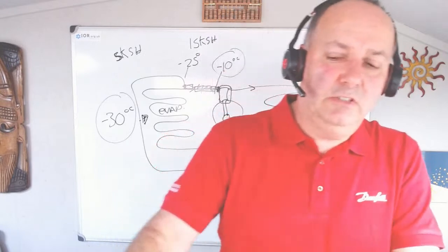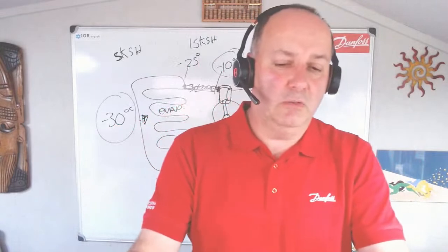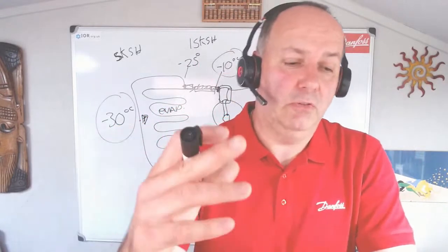Okay, Dwayne, which connection of the evaporator during hot gas defrost is optimal for commercial refrigeration systems? And that's from Gregory. It depends what we're talking about, whether we're talking about the simple reverse cycle, whether we're talking about literally putting hot gas into the evaporator on a 1-to-1, or we're talking a 2-pipe system or a 3-pipe system.